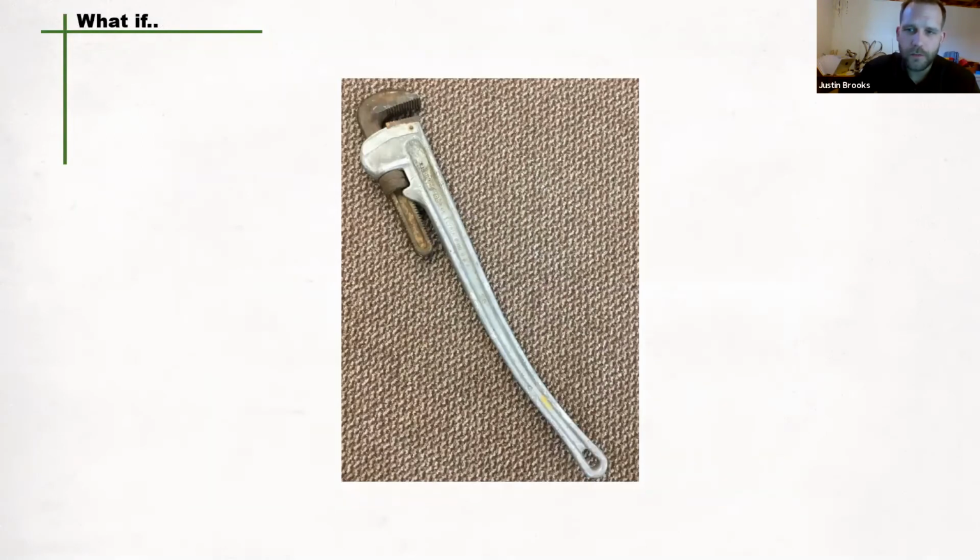Train on the limitations of the tools. As an example, do the workers know how much force can be applied to a pipe wrench before it breaks? Teach workers to look for the ratings on the slings and lifting equipment and know the weight of the load to be lifted. Incidents have occurred where the operators were expecting the engineered shutdown systems to look after things if anything went wrong. The shutdown parameters need to be understood, including things like delays, response time of incidents, etc.